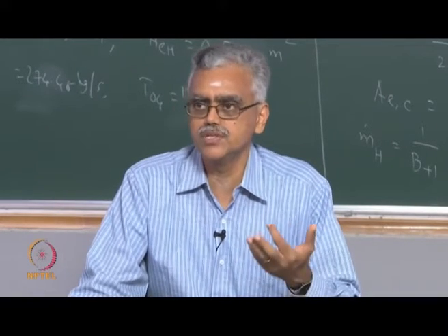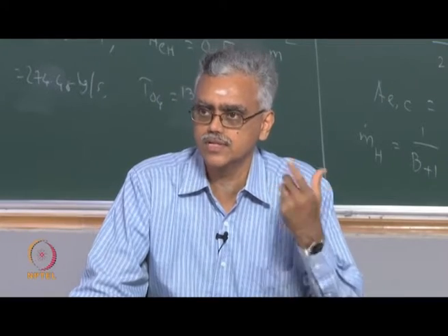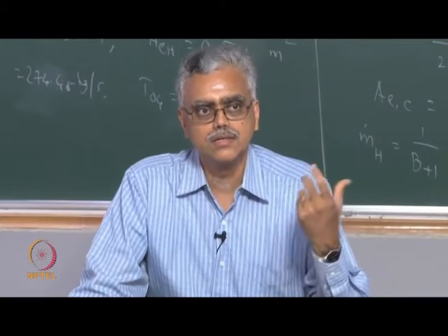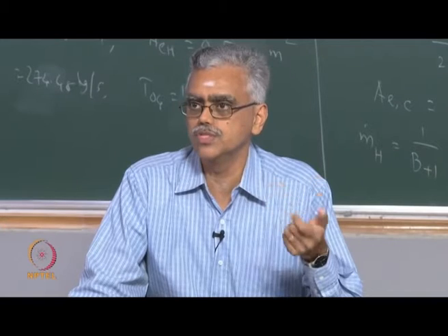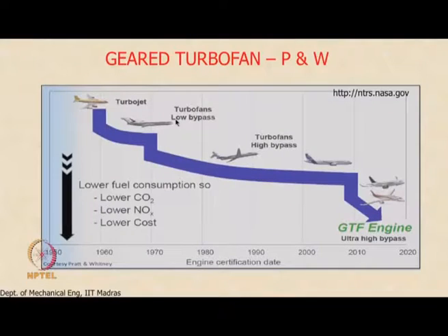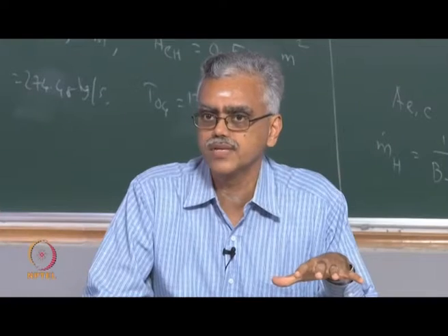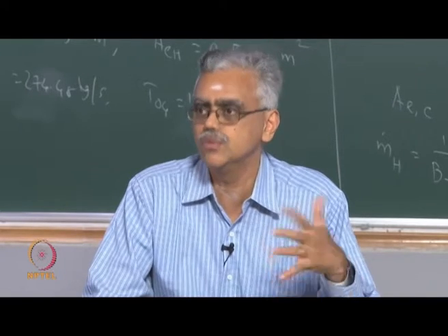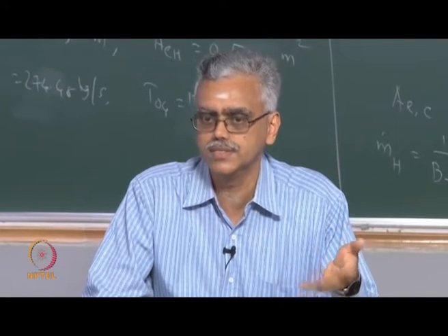So the higher bypass ratio engines bring in those kinds of challenges, transonic fans as well as differential speeds, multi-spool technology and so on. So the low bypass turbofan engines do not present such challenges. So it was relatively easy for the industry to migrate from turbojet to low bypass turbofan engine. But it took a while before they could migrate to high bypass turbofan engines. And we looked at these technological challenges and how they were overcome in our earlier lectures.